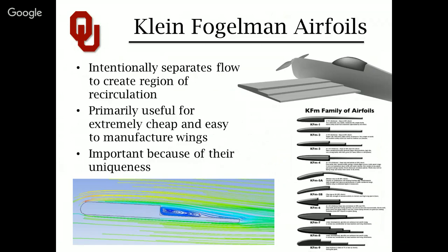Use my magical pen again. When I say recirculation, I'm talking about this almost doorstop shaped loop of fluid. That's exactly what's happening. It's kind of like the classical reverse step test case for CFD. So you see that in the flow's consideration, these are streamlines. Maybe the shape isn't quite as bad as the outline makes it out to be. If this region of recirculation is just spinning, yet the flow around that region is staying mostly attached, it's almost like an aerodynamic wedge that keeps it smooth.